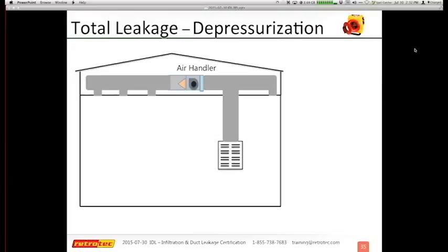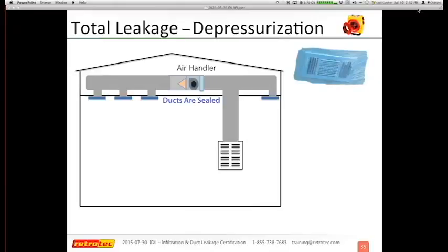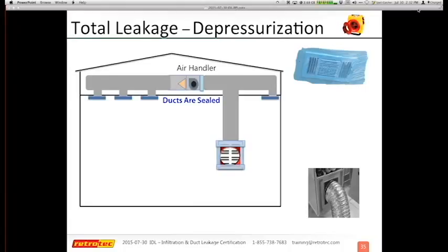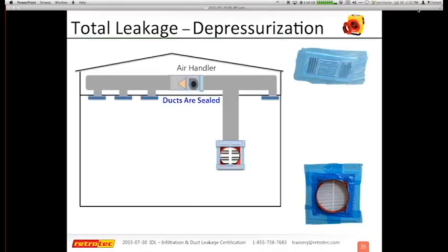So we always start with sealing off the ductwork, anything that's not going to be connected with the duct tester itself. We're going to connect the flange and seal that off to the return or wherever we're going to run our test from. Sometimes you may do that at the air handler because that's the easiest place to make a connection if you have lots of returns. Otherwise, it should be the largest return and closest to the air handler. You connect your flex duct, connect your unit.